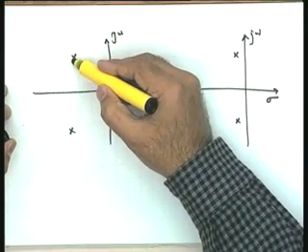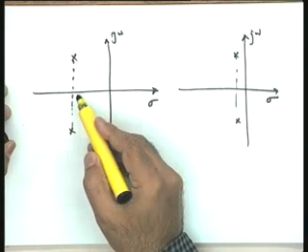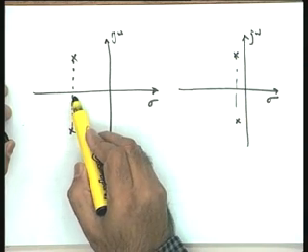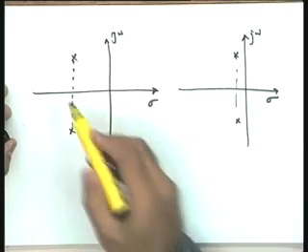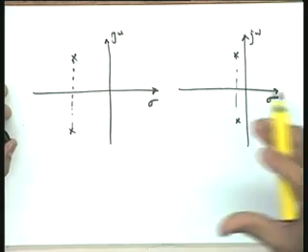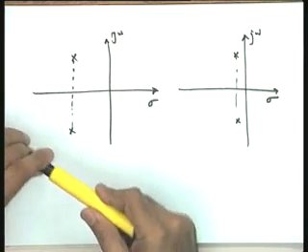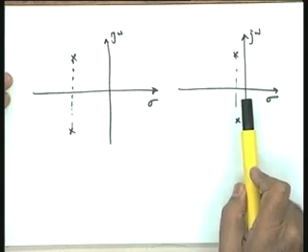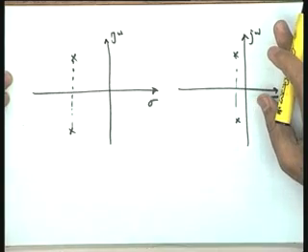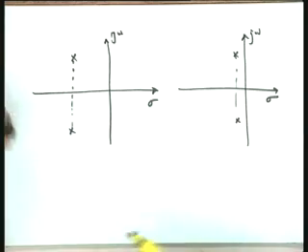you can say that the relative stability of the system is guided by the real part of these poles, the distance of the real part of these poles with respect to the imaginary axis. You already know that this real part guides the envelope of the oscillating response. So, we know that the closer the dominant poles are to the j omega axis, poorer is the relative stability of the system. Let us interpret this in the frequency domain.